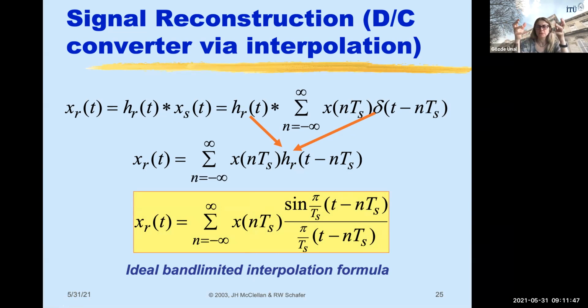It's trying to say that the sampling frequency was correctly selected, the signal was already band limited, the sampling frequency is selected at least twice that bandwidth, and we use the ideal reconstruction filter, which is a sinc in time domain, sine t over t, of course shifted. Shifted to multiples of this sampling period, Ts, you see. And the frequency was pi over Ts.